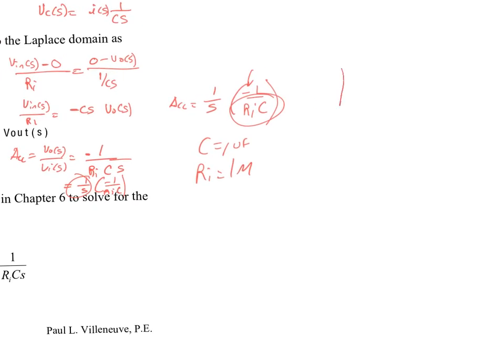In real-world op amps, you always have some small, 10 millivolts DC between those two terminals, right? It's going to be small. There's some DC offset. So there's a way you can put a compensating resistor. You can drive those. Am I talking about this stuff? John hasn't mentioned it. Compensation resistors to get rid of DC offset.